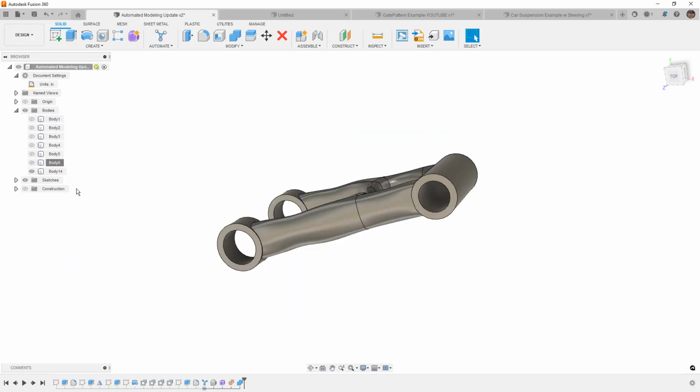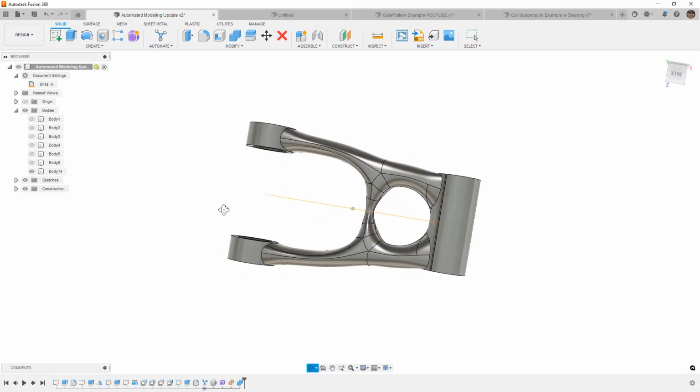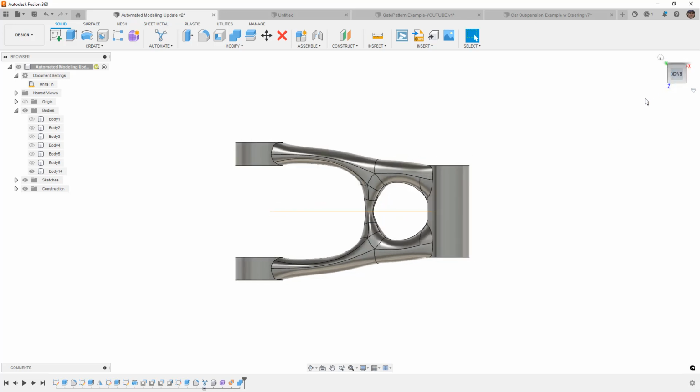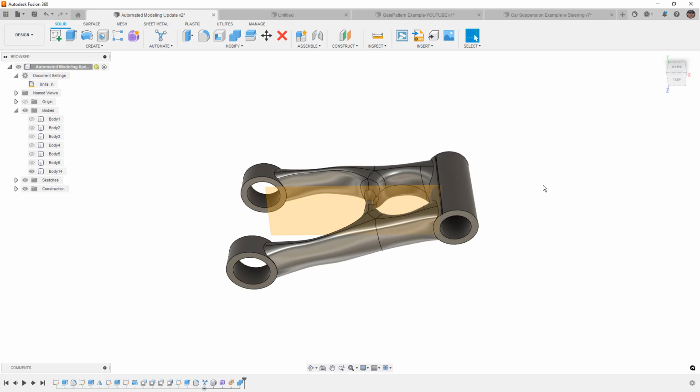At this point, it's not instantly apparent that it is symmetric, but it does use symmetry when it's creating these designs if your models are symmetric. Now, what that means is that you can create your initial designs, in this case, the areas you want to connect, in a symmetric fashion about a plane. In this case, I created them about the XY plane and just simply mirrored them across or extruded them as a symmetric body. Now, again, this is not instantly apparent because there's no option to toggle on or off symmetry, and you slightly get a different result when you talk about using just half of the design. Something that you might do in practice is create half of your design.